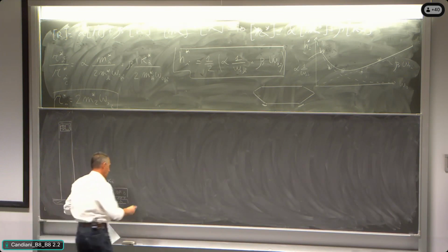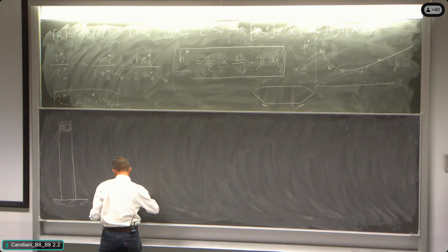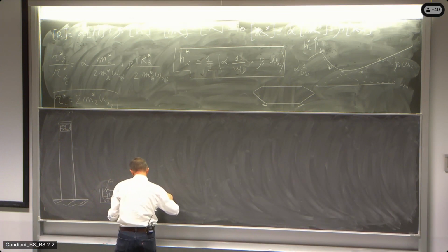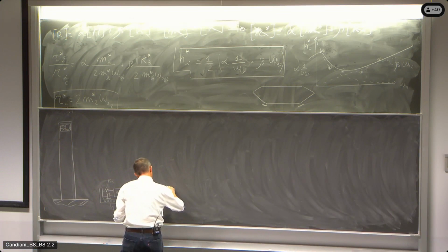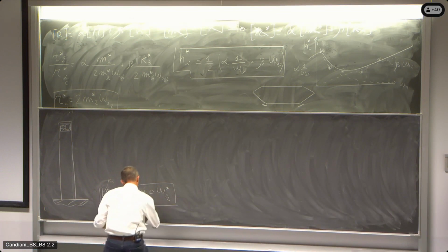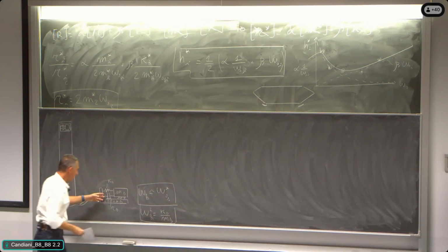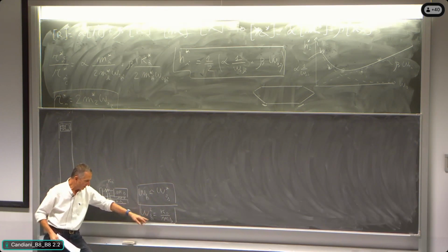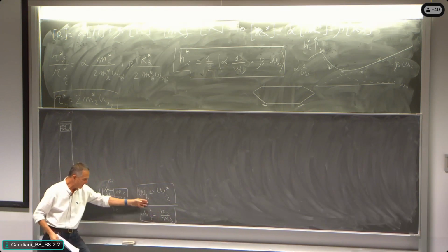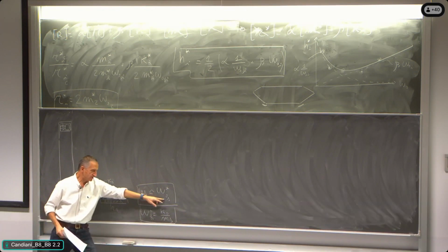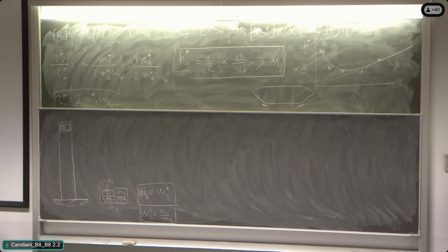We make it so that omega, so we are dimensioning this object so that the intrinsic natural frequency, K damper divided by mass damper, is equal to omega 0 damper squared, with omega 0 damper almost similar to omega 01, where omega 01 is the natural frequency of the first mode of the structure that you want to protect, all right?